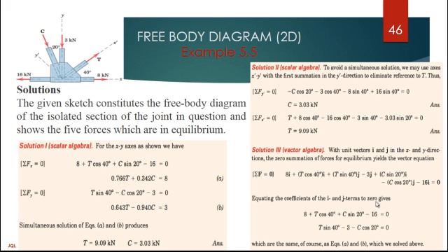The vector algebra will be summation of forces equals 0, where we mean the I and the J. Then at the end, I use the I to be equals to 0 and the J to be equals to 0. You solve those two equations, you would find the same answer, your T and your C, to be 9.09 kilonewton and 3.03 kilonewton respectively.